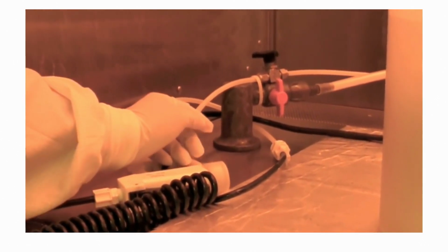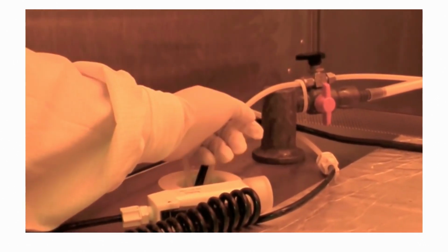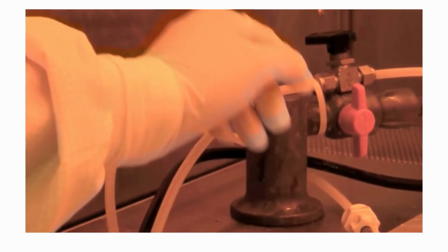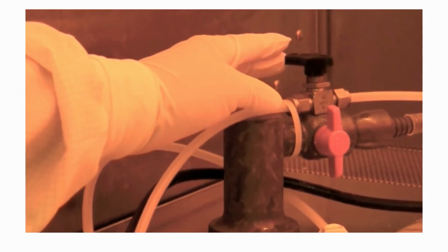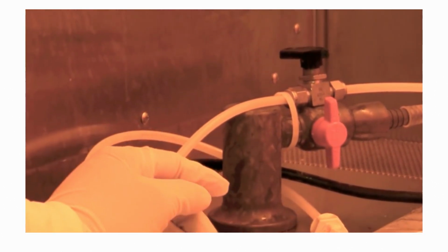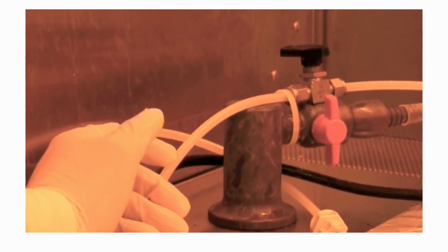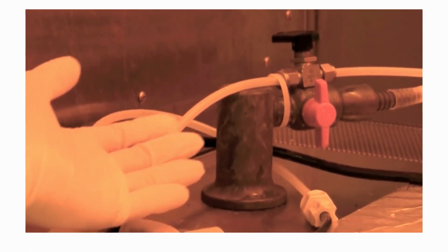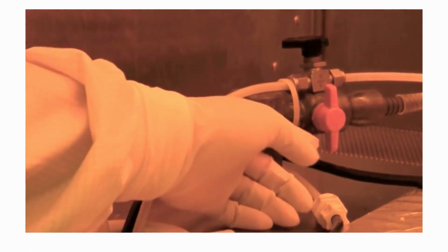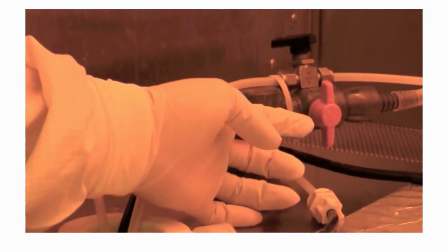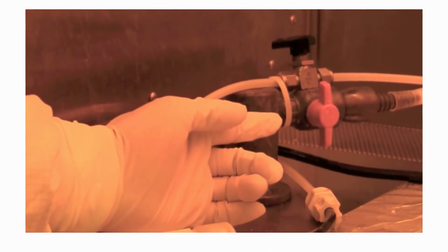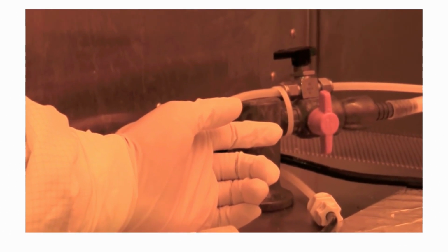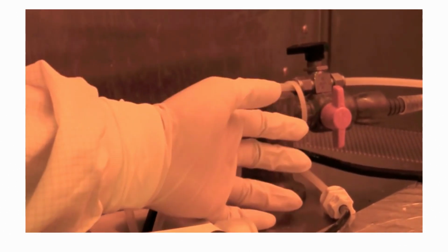The reason why we have to keep both these lines open when we use the tool is because it provides functionality to our spinner. This line here is a nitrogen line. It provides nitrogen gas to the chamber of the spinner. This is important because it keeps the environment inert inside the spinner and prevents any kind of gas from leaking into the motor and possibly causing a reaction. The line here, the vacuum line, is important because it sucks in and holds your sample on the chuck. Without this vacuum line, your sample will not stick to the chuck as it spins. It will fly out. So it's important to have them both functional and working.